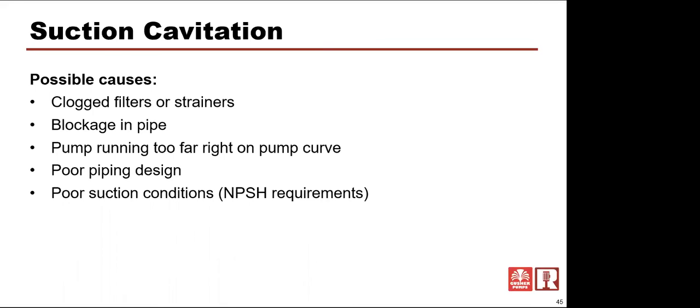or operating too far on a curve. Like on that one system that I mentioned, normal operation would be operating 3 pumps, but at night they thought it would be a good idea to run 1 pump and turn the other 2 off to save energy, which is great. The problem is that it lets that pump run way off the curve, and all of a sudden they're getting cavitation and seal failure and vibration and cavitation in the system that ends up destroying that pump.